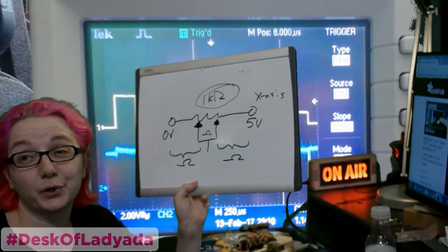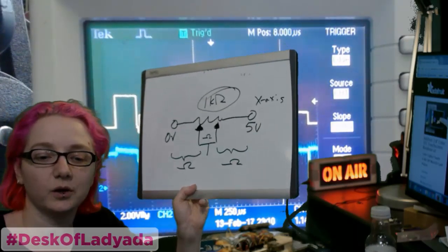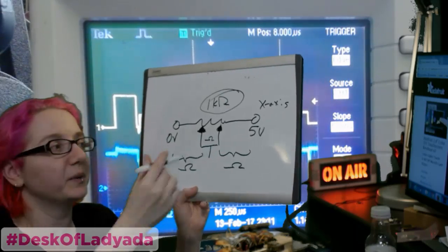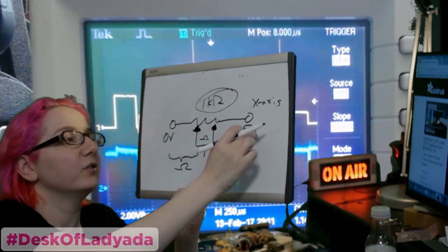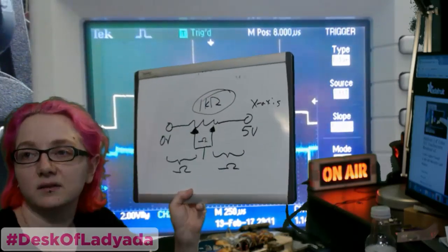It's usually pretty close, as long as you have pretty good analog reads, because again, the resistance falls out of the equation. You're just measuring between 0 and 5 volts. It doesn't really matter what this resistance is for single touch.